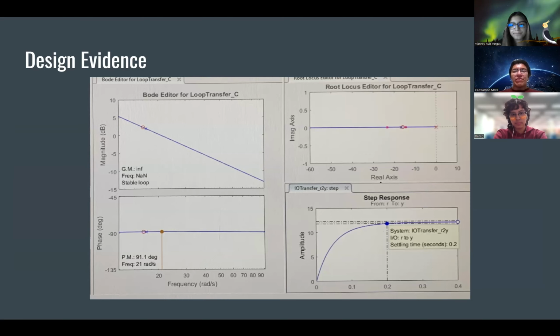As we can see in the locus plot, none of our values is in the unstable region; everything falls under the stable region. In the magnitude plot, it goes down significantly, which is a good sign. It's supposed to produce a linear line. The phase region is a straight line, which is a good sign. If it was lopsided, it would not have been a good result. Since everything fits our customer requirements, we are able to say the proportional integral design was the best way to go.